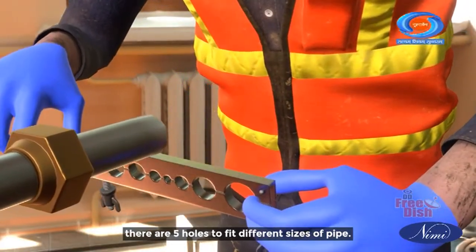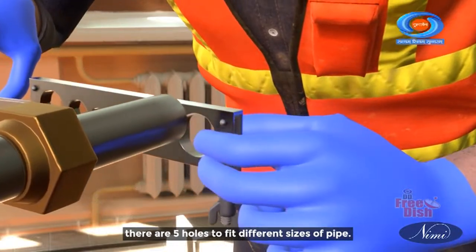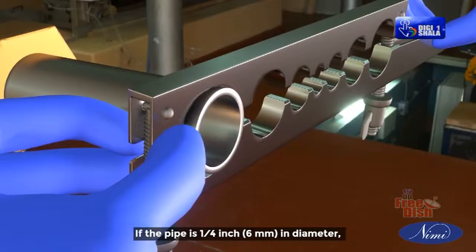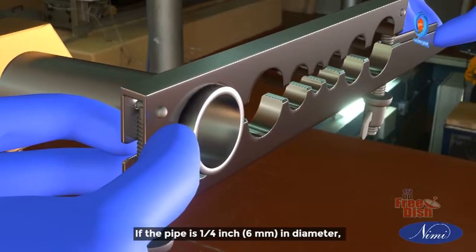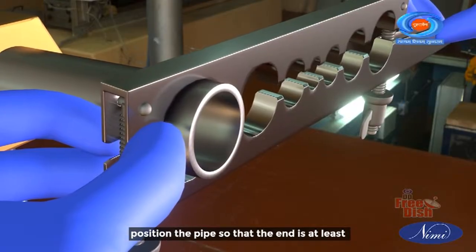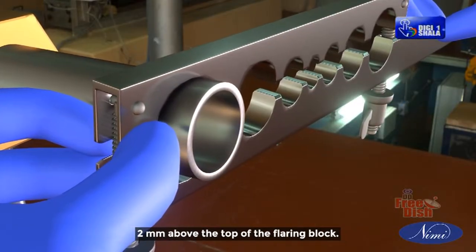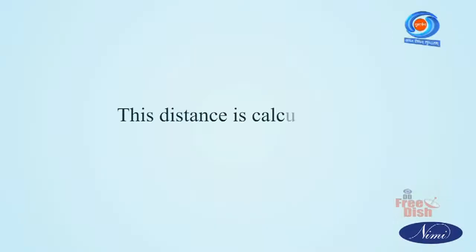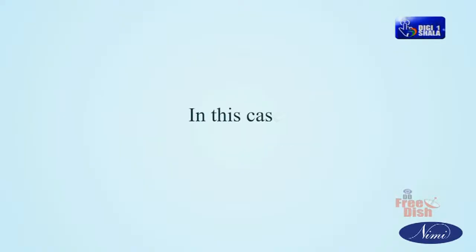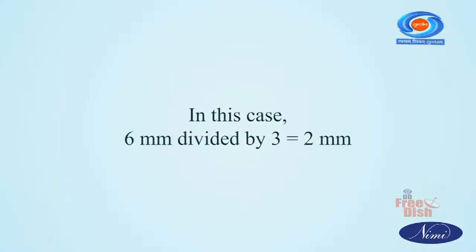There are 5 holes to fit different sizes of pipe. If the pipe is 1/4 inch, 6 mm in diameter, position the pipe so that the end is at least 2 mm above the top of the flaring block. This distance is calculated as pipe diameter divided by 3. In this case, 6 mm divided by 3 is equal to 2 mm.